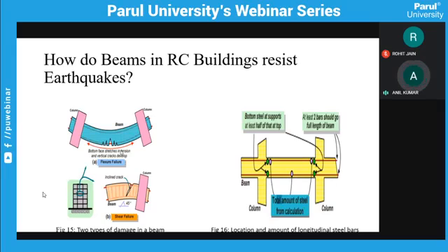In the ductile failure, we can see that it results in various vertical cracks, starting from the face, and they can go towards the mid depth also. So these cracks are visible. That is, it starts from the face and slowly goes to the mid depth of the beam. The second one is the shear failure. These are the two portions of the building where we are showing the beam, with flexure failure and shear failure.